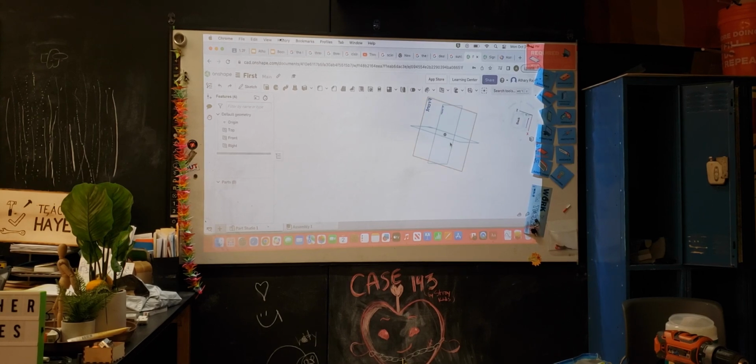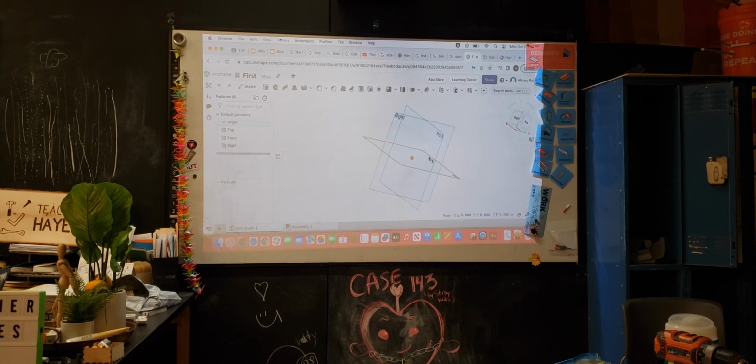In order to navigate this area, you use a 2-finger click if you're on a mouse pad, or right click, to pan around and look at different angles. So that's how you move. You double click and then you can turn your angle of view. F is the hotkey to return to the original point, and control and then 2-finger clicking shifts left and right.